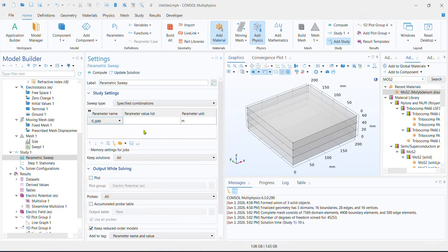Now I can sweep this decap parameter in meters. Since I'm doing this in meters and defining everything in meters, I have to be careful of that, by the way. Now the range, I'm going to sweep from what to what? Initially it is 40, no, so I want to sweep from something else. I want to preferably sweep, let's say, from 30 mm. I want to sweep in 1 mm steps, right? And I want to go all the way to 40 mm. I think we can do that.